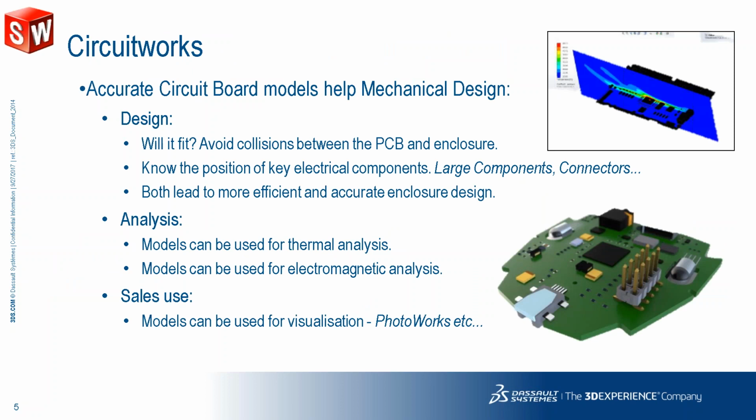starting from our old add-in, which we have had, I believe, since 2005, which is SircuitWorks. SircuitWorks is a solution to produce a SOLIDWORKS assembly from the IDF file. We all know that most electronic solutions provide the IDF format, and what SircuitWorks does is import the IDF format into a real 3D environment. This can be really beneficial for designers, so they can understand whether it will fit. They can answer the question of knowing the position of the key electrical components, and they can use the component library directly.